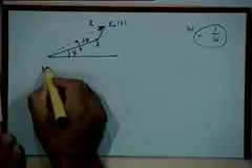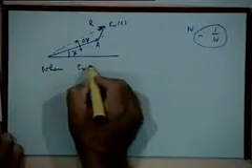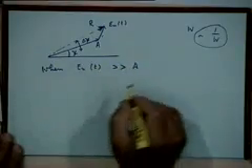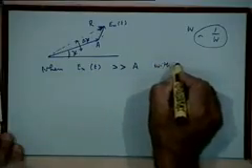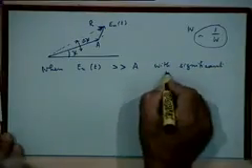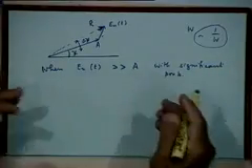So basically what we are saying is, when there is a finite probability that ENT suddenly becomes greater than A with some significant probability, that is, the probability of this event becomes significantly large. When ENT is much less than A, when signal power is much larger than the noise power, the probability of this event happening is going to be negligible. The threshold effect occurs when the probability of this event becomes significant, right?